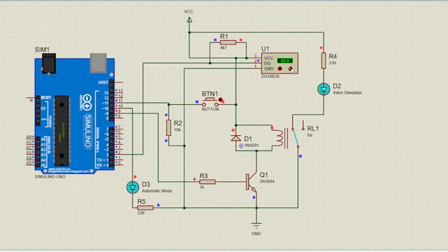The circuit consists of an Arduino Uno where the control logic is housed, a DS18B20 temperature sensor with a pull-up resistor of 4.7K indicated by the manufacturer, a push button to set the desired state with a pull-down resistor, a 5V relay with a 1N4001 protection diode, a 2N3904 transistor to activate the relay, and an LED to indicate the automatic enabled/disabled state of the firmware.